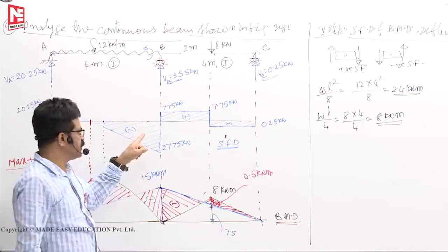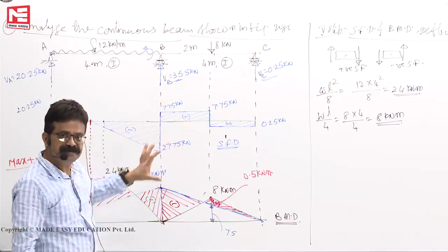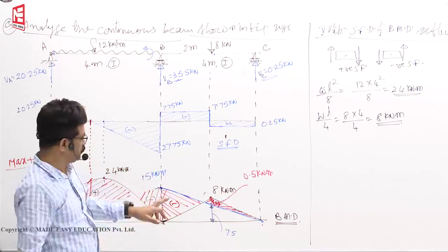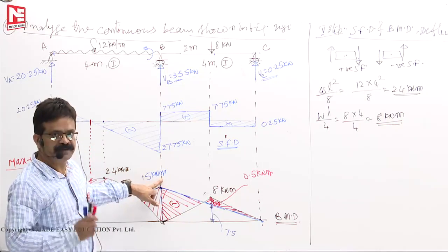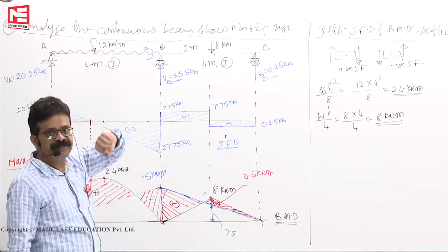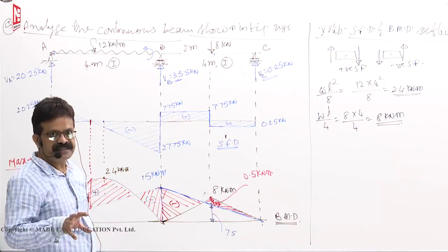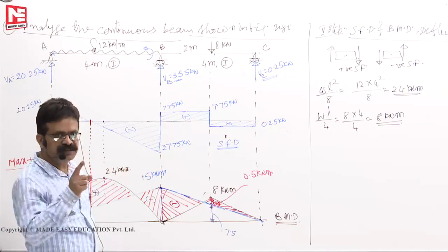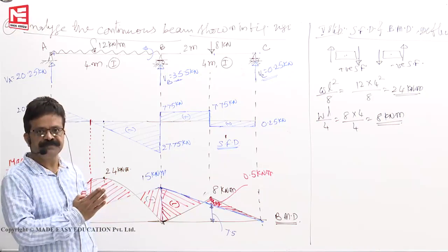If shear force changes its sign from negative to positive, bending moment is minimum, means mathematical minimum. Minus 15. Minus 15 is minimum. I told you mathematical minimum, what it is in the influence line diagrams also. Once 0 is there, minus 15 is there, say, what is minimum? Not 0, minus 15 is minimum because it's lesser than 0.